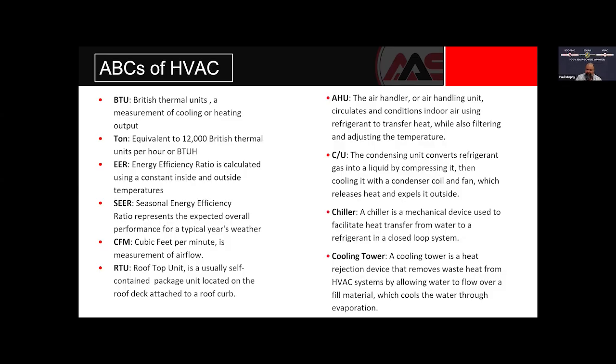CFM stands for cubic feet per minute. That's a measurement of airflow. You have RTU, which is typically a rooftop unit. Typically, it's a self-contained package unit located on the roof deck, attached to a curb. Sometimes it could also be considered a condenser on the rooftop, but typically it's a package unit. AHU stands for air handler or air handling unit. It circulates and conditions the indoor air using refrigerant to transfer heat, while also filtering and adjusting temperature.